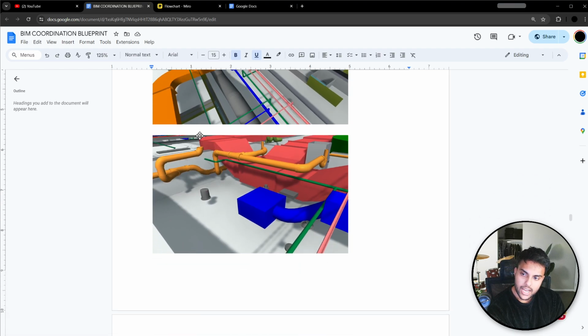Like this duct has to drop down, and this ceiling has to drop below that, and then you have this hydraulics point because there's a toilet above here. So that hydraulics point has to go down here. It has to do that U because that's how it works with sewer. Right? And then it does the U, and then below that U is where you have the duct. That's why you have to move this duct down, because if you have this duct going straight, it would clash